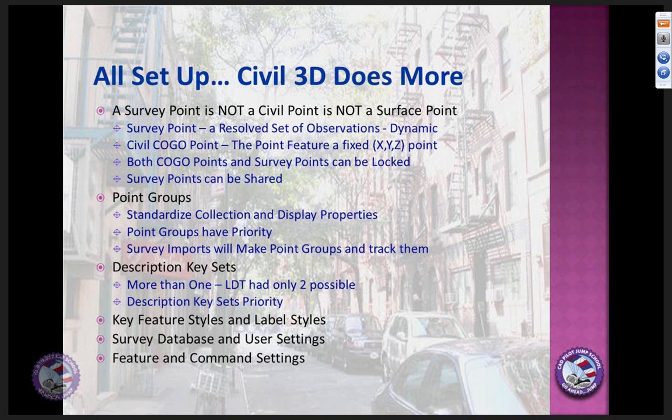There's no such thing as a COGO point. The software looks like there's a COGO point, you see one, okay, but under the wrapper, so to speak, Civil 3D is always thinking of this thing as part of a group, and that's frustrating because it has a definite different approach to what's going on.